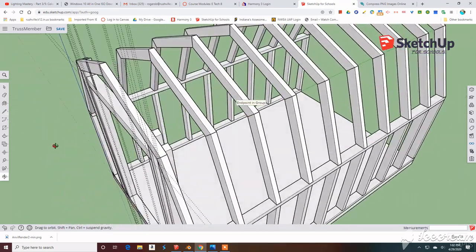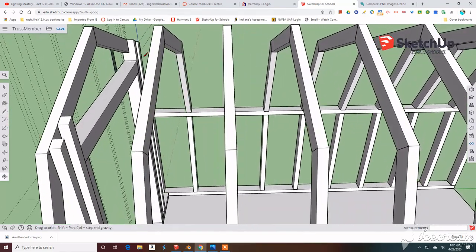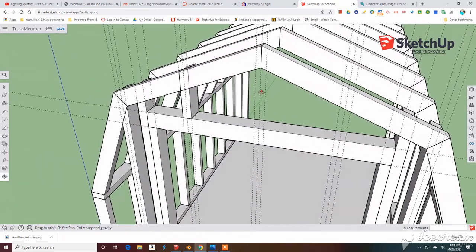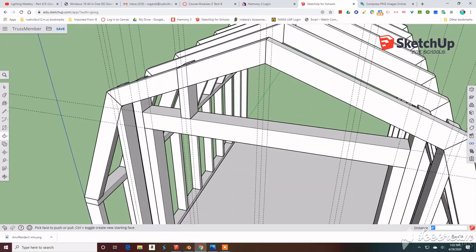All right, so you see that was pretty easy. Going to the back side now. I'm just going to push-pull this, using this edge right here as a guide, so it's making an inference, using the inference tool for SketchUp. And so there I have that piece. Well, so just go through the same process.